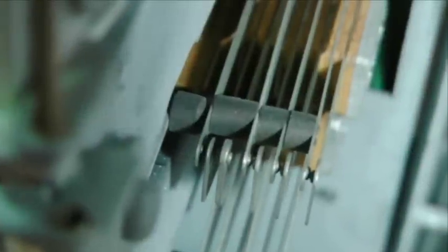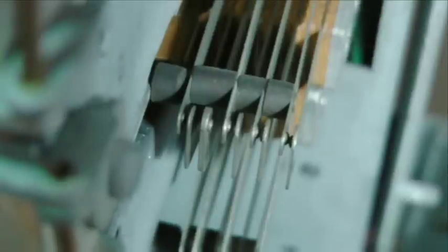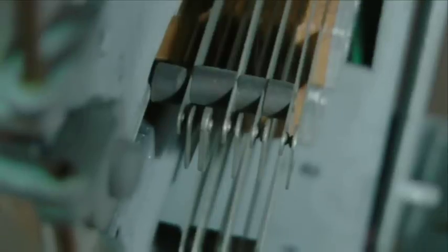Notice that many of the contact springs are ganged together by these bushings. You can see the visual effect of this ganging as I manually operate and release the armature several times. Contacts 1 and 2 bottom are easily made before the combined tension of the ganged contact springs is encountered.